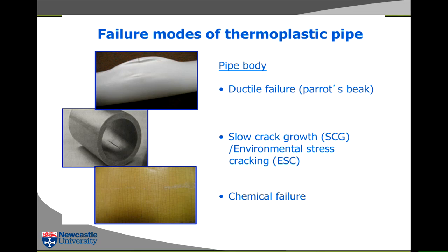I can just about see on here, we have cracks in the axial direction and cracks in the hoop direction when the pipe is under pressure. And that's a pipe that's been subject to UV. That's the sort of behaviour that you get with UV. So if you come across a thermoplastic pipe and it's got this pattern of cracks at right angles to each other on the outside, it's probably UV induced cracking.